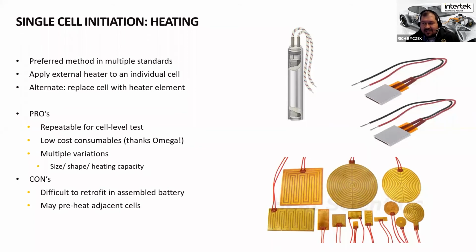I show examples here on the screen. You've got module and plug heaters. The one on the upper left, for cell based, single cell based battery systems, I can have a heater that's essentially the size of a single cell and use that to be the triggering event for adjacent cells. So I'm not necessarily triggering a single cell into runaway, but I'm simulating the heat effect of a single cell going into runaway.